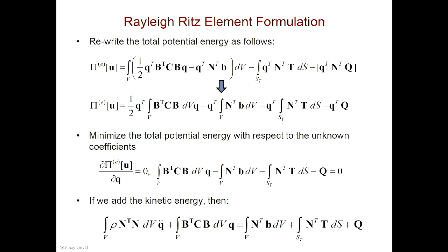But there is a dynamic finite element equation for 3D. And for 2D, it's not very different from that, because for 2D, basically, instead of volume, you have area times the thickness, h, right? So, in essence, I've covered 3D. We've done it. This is as hard as you can get. I don't know how harder you can get with this equation. N is fully known. These are the matrices of shape functions. This is B bold. You can calculate that. You can calculate C bold.